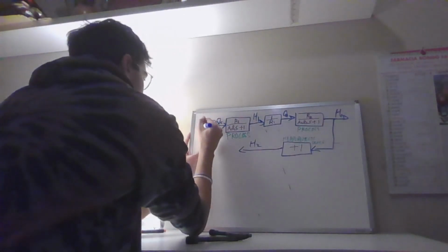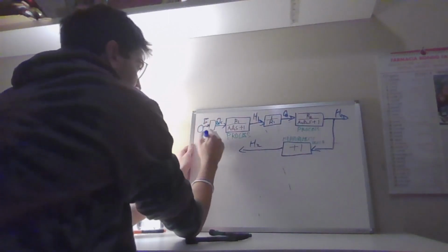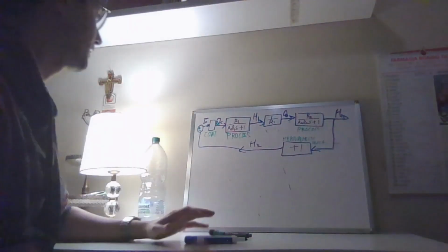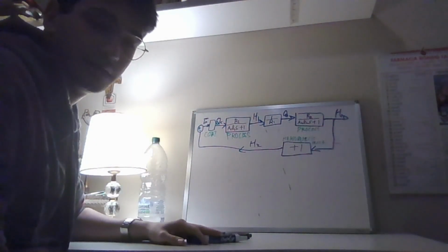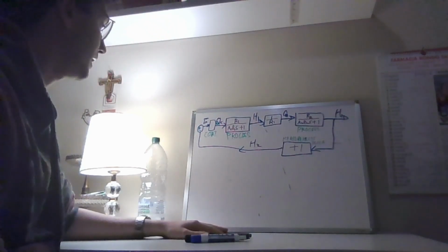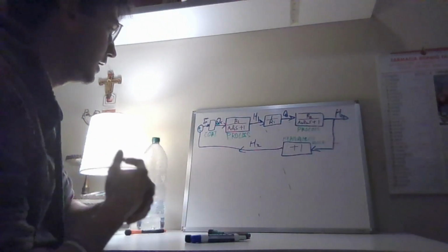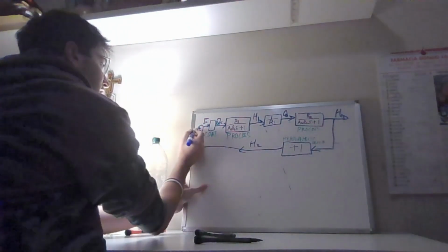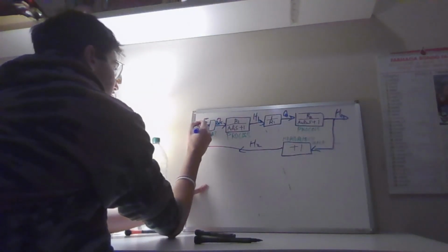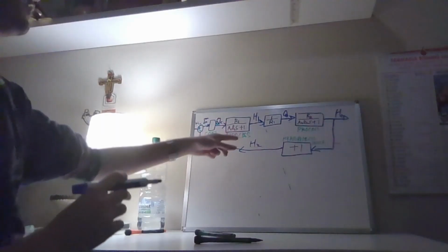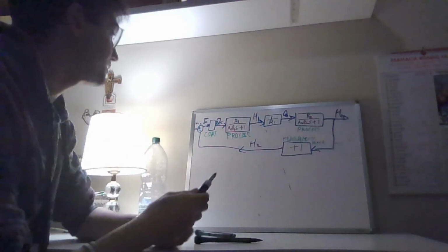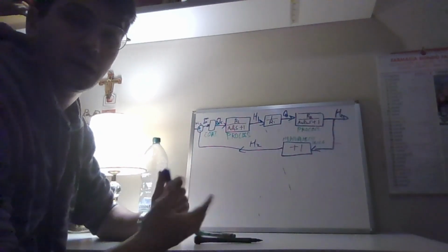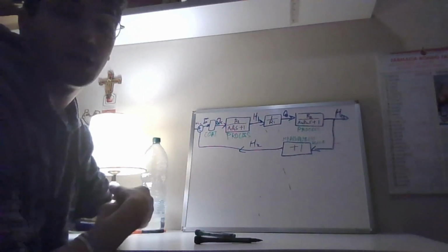Because it comes from this, I think I must be calling it wrong, but it pretty much just takes the difference between our set point, which we're feeding it, H2SP, and the H2 that is coming back from our measurement device. And that is where our epsilon comes in.